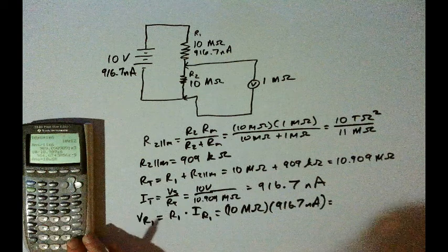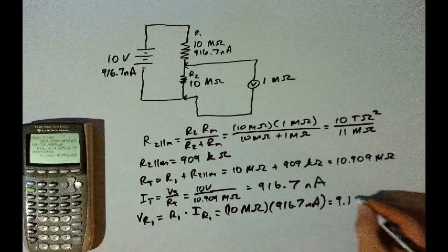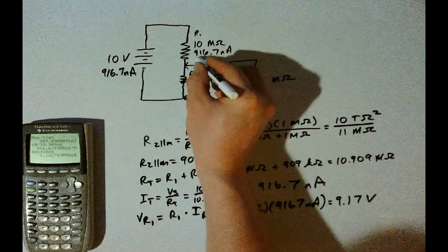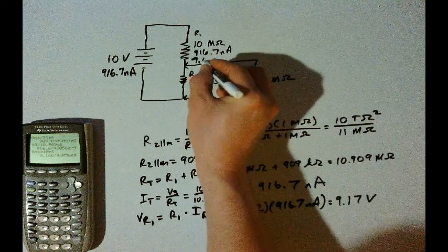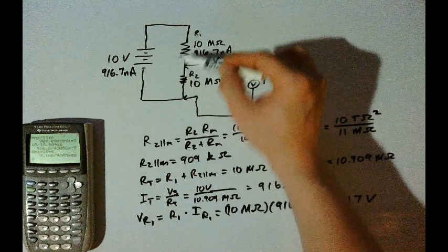And again, it doesn't matter what path we take here. If we go through the voltmeter and then R1, these two voltages add up to 10 volts, or these two voltages add up to 10 volts, either way. And so that is the answer to the question. The voltage drop on the meter will be 830 millivolts.